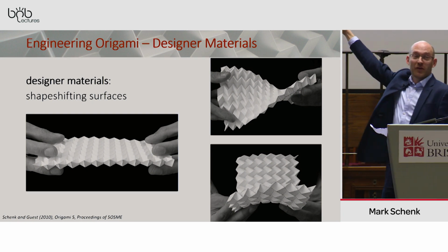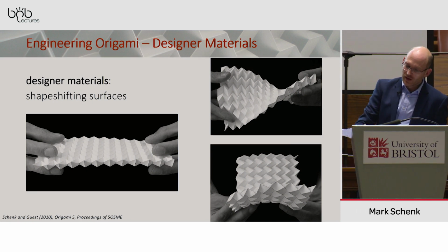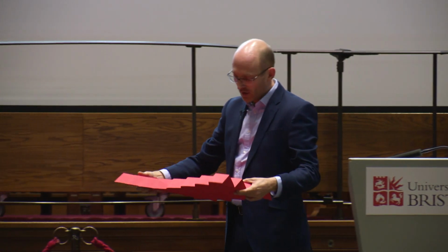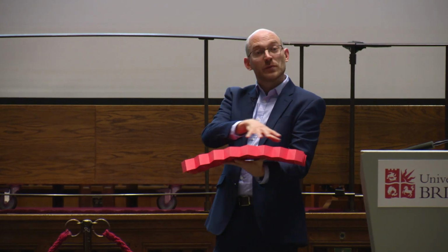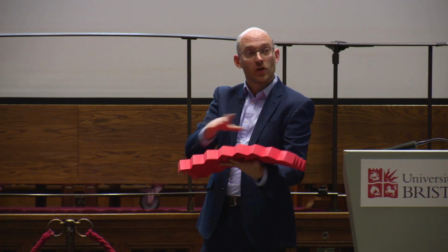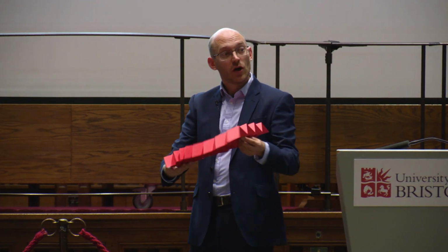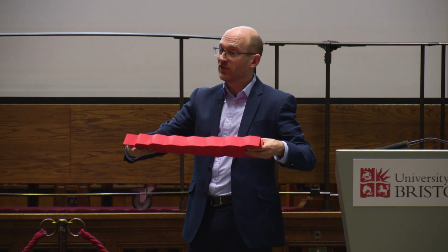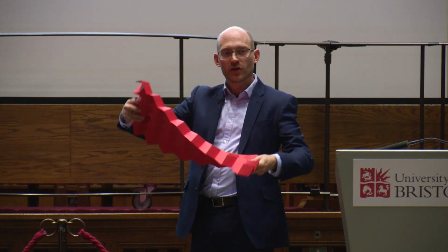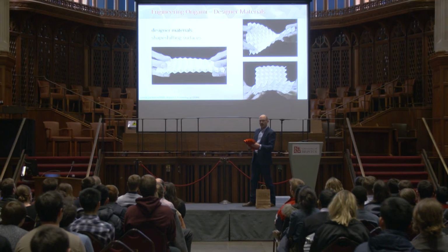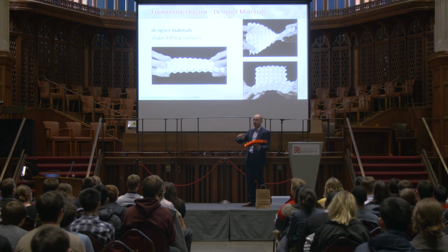So my PhD was entirely about this pattern and understanding it. The idea is that you have this origami pattern, and by controlling not only the material you're using but also the pattern, you can control how stiff this is or how this behaves. By changing the pattern, I can make it stiffer or less stiff in different directions. I can twist it. I can deform it. So the idea is that we can use origami as a way of creating materials which have properties by design. By changing my pattern, I can design different behavior into it.